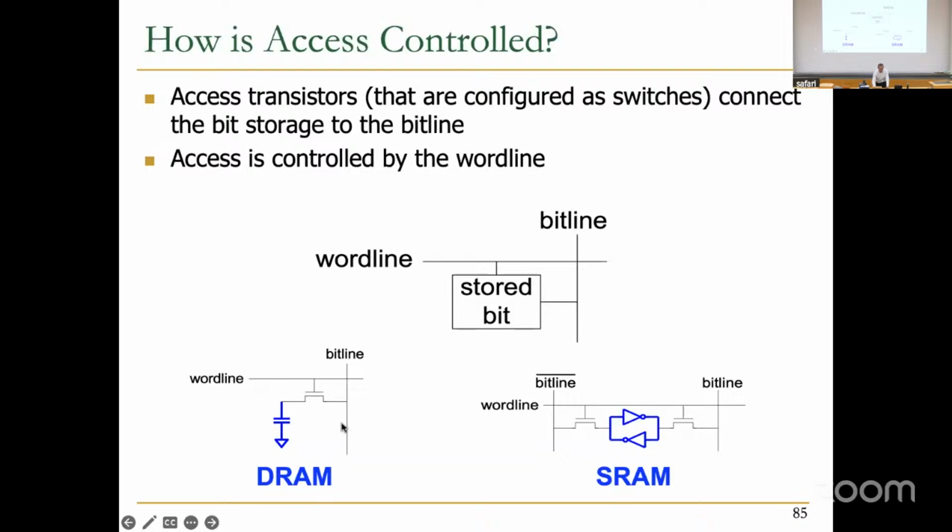But now you know how a DRAM operates at a fundamental principle level, right? Maybe you cannot draw the analog operation, but that's not the purpose of this course. The purpose of this course is that there's a switch over here, which is the access transistor. If you enable that access transistor, this bit over here can get sensed. If it's charged, it's a 1. If it's discharged, it's a 0. Now you can sense a 1 versus a 0 if you design the appropriate circuitry.